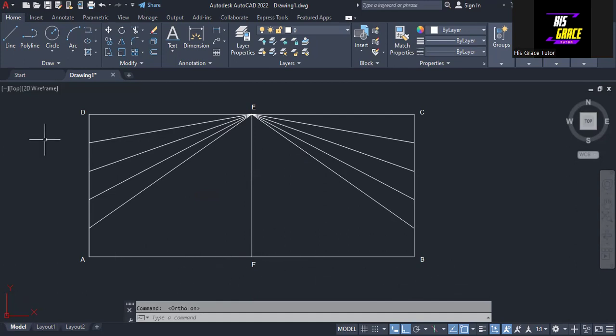That is what I want to do. So now I will select line again. If you don't select the auto mode, it will not give you the right vertical line. The line will not be vertical, so there may be error. That's why you need to activate the auto mode, whether you are drawing a horizontal line or a vertical line. It has to be activated.